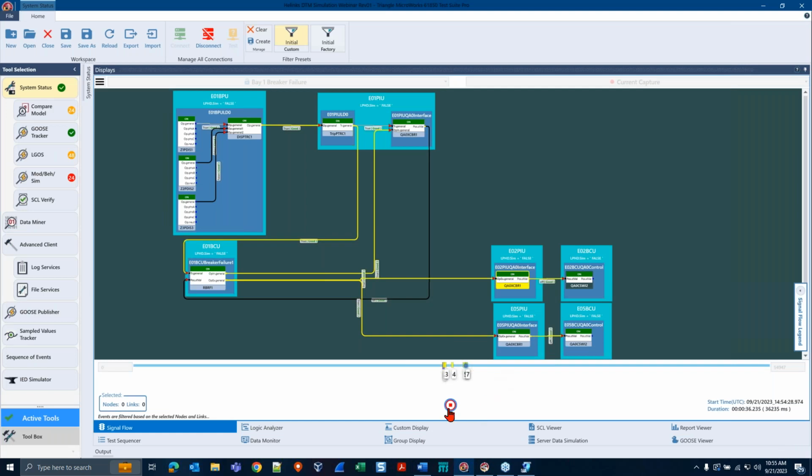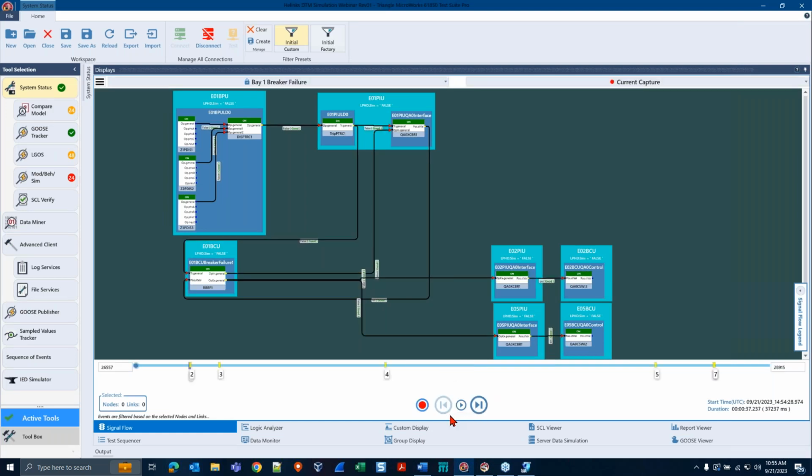So now let's come back over to Test Suite Pro and take a look at what happened. It all happened pretty quickly, so I'm going to stop the capture and step through it to give us a little bit better idea of how these signals actually flow. The first thing as I step through is when I click that button, the distance protection operate.general message picked up. Now, this was documented via source ref that this should be passed into the distance protection PTRC that exists on the BPU, or Bay Protection Unit. And that's represented by this box right here, which represents that logical node.